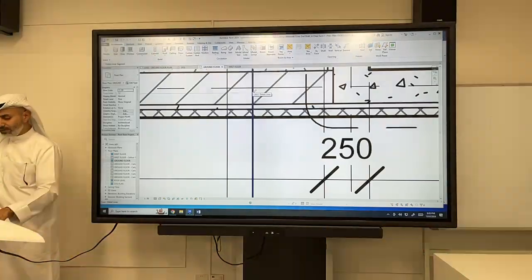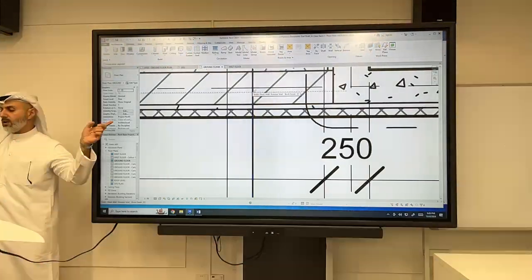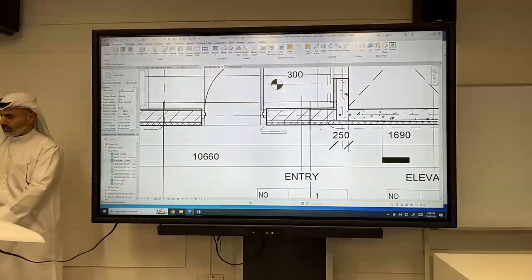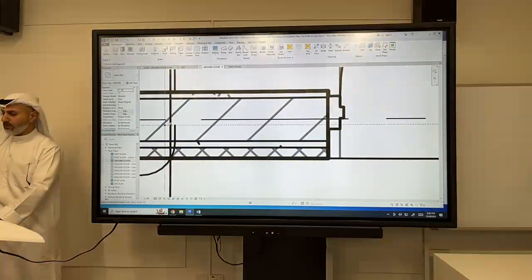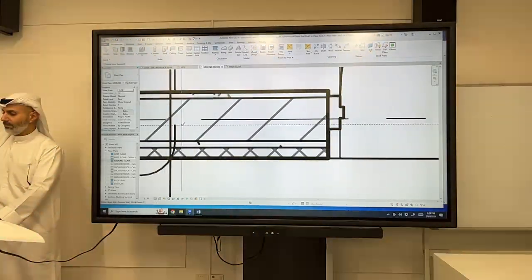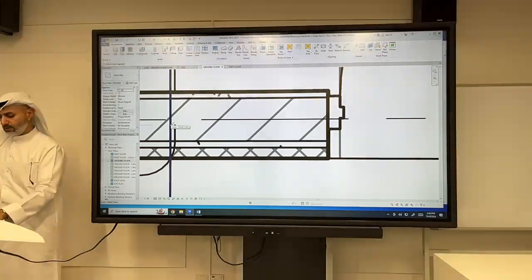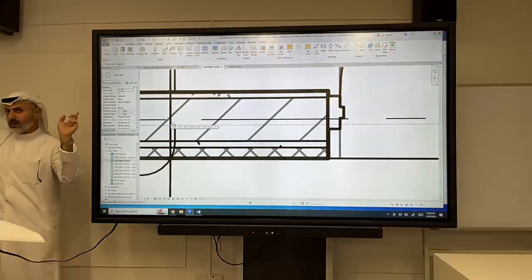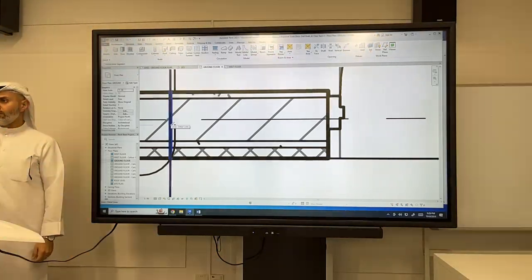So when you're on this line, hit tab. At your one wall, then you click. Okay, I'll do it again on the other side. So SL. I'll hit exacto. Find the center of the wall. Trace it, go all the way to where the line is. So the line is highlighted. Hit tab. Now it's selecting the wall and then you click. This way you guarantee that you're cutting where the line that you drew as a guide.